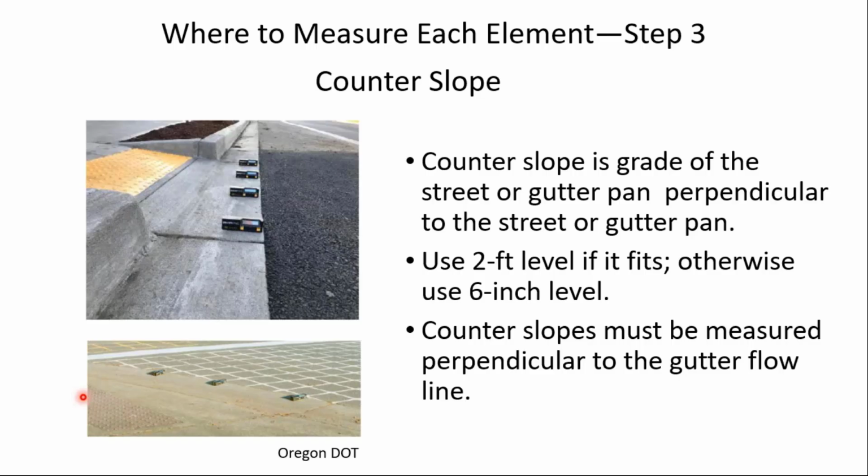Question from Joseph. Many times water accumulates at the gutter. How is this eliminated? Careful attention to elevations when you're in construction, or if you look at textbooks, I think they say put grates and inlets upstream of the ramps. I realize that's not always possible, but I would say careful attention to elevations when you're in the construction phase of the work.